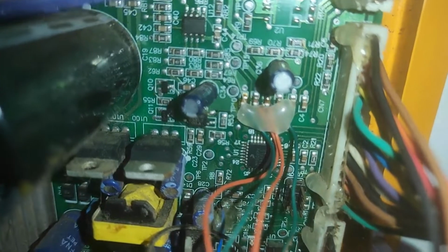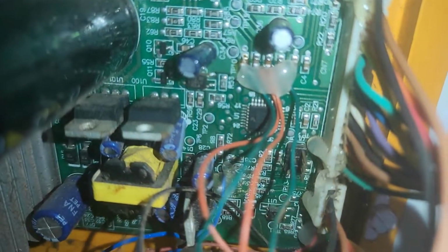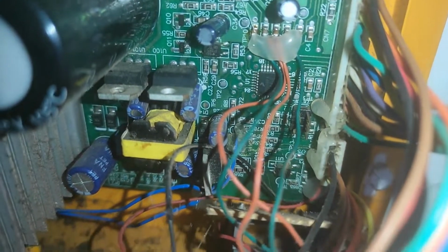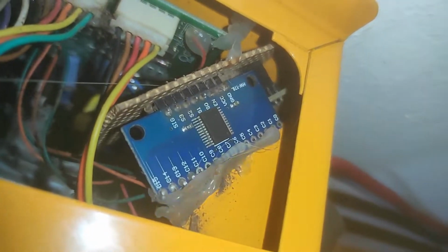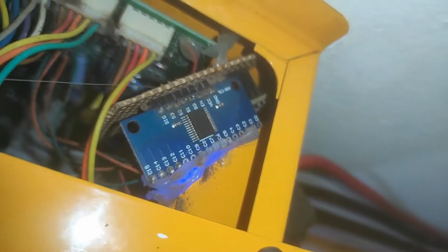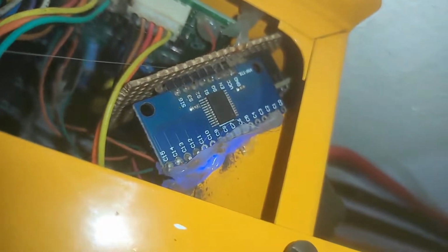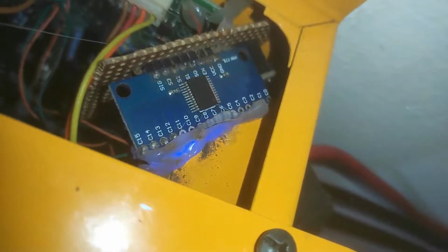You can see the capacitor very close to the microcontroller. These are the capacitors for filtering the ADC pins which are going to the microcontroller. So I have taken these data pins to the multiplexer input, and from there it's connected to the A0 pin of the NodeMCU. Also for the power supply, there was a 7805 regulator IC inside the MPPT, so I have taken power from those pins. Yeah, that's the hardware setup basically.